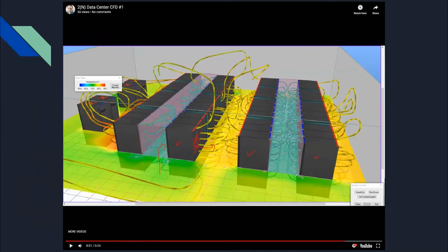Because if your computer is running for a while, it's going to become hot, and you will have hot air. Similarly, the next row of computers is set up in such a way that the hot air comes this side, and cold air is taken inside, essentially making this entire gap what you call a hot aisle system. So this is called hot air containment.